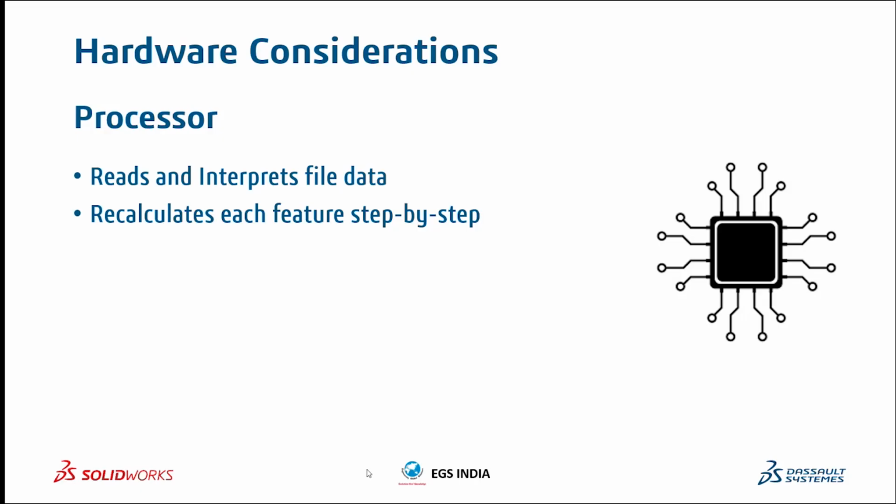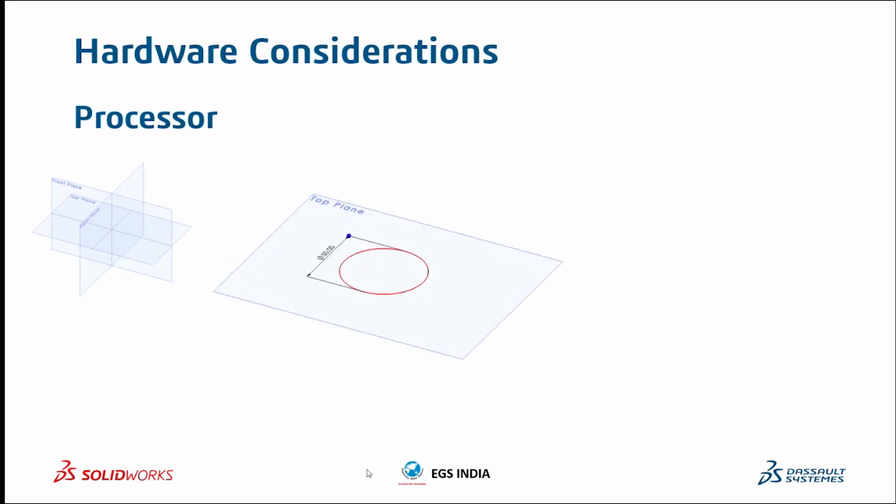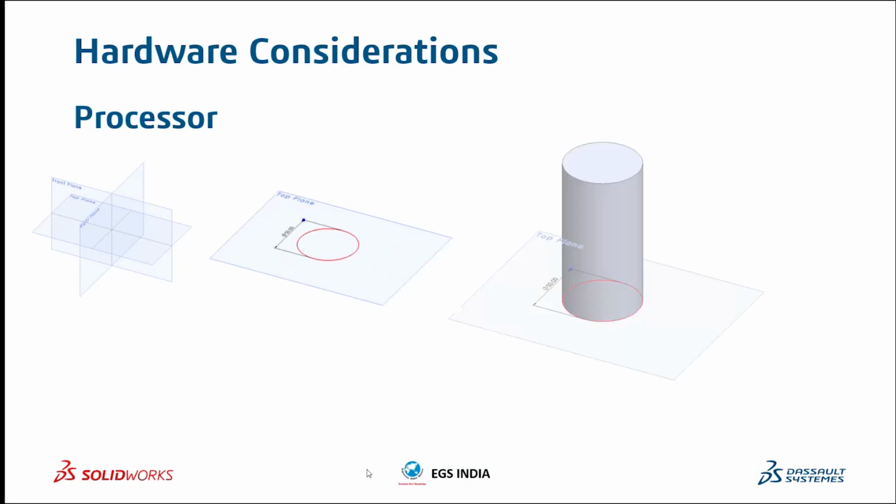So what is your normal workflow when you work with design or CAD in SolidWorks? Let's say that you're going to create a simple part file. What you first do is select a plane. First, we define or select a plane. And with the plane, we create a sketch. With the reference of a sketch, we build the 3D geometry, which is built by a feature. Over here, we showed a simple extrusion.